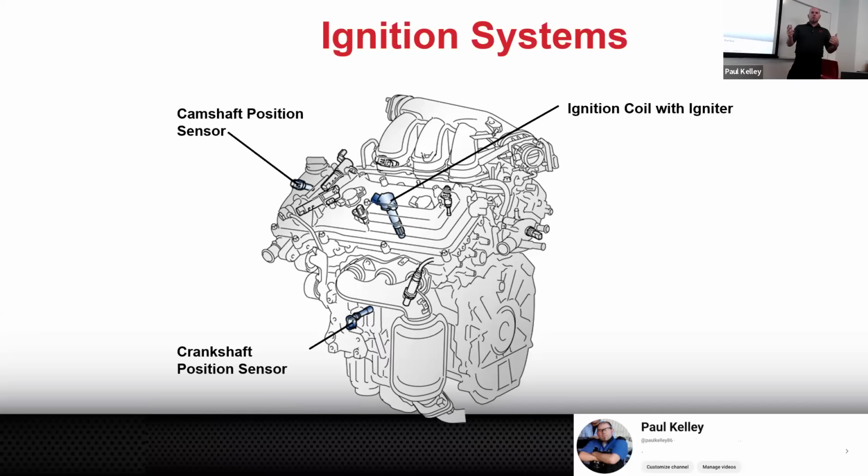And they're like, well, remember I told you about that one last week? She called and said I had a misfire and it didn't follow the coil. And so she determined it must be the spark plug, right? Well, the thing is, there's other stuff that could cause it. If you don't have the right primary ignition voltage, you are not going to have the right secondary ignition voltage. Primary makes the secondary. So if the primary is no good, the secondary is definitely no good.